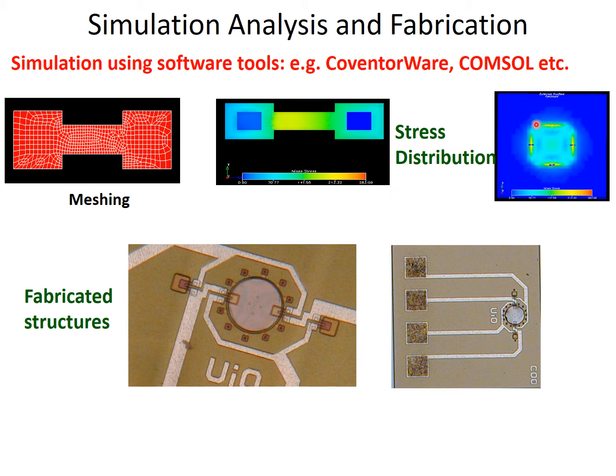Here is another type of diaphragm, where, as we showed in the previous slides, 4 piezoresistors are mounted, and when the pressure is applied at the middle, we can see how the resistance of those resistors changes. Those things we simulate, and we can do simulation multiple times, right? Because that will not take a large cost. That is just the computer's job, so anytime we can make some change and accordingly the output change will be reflected.